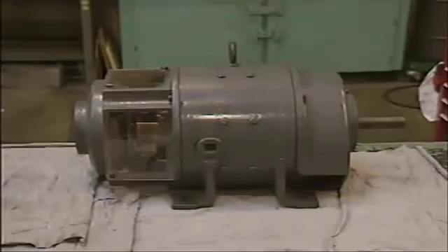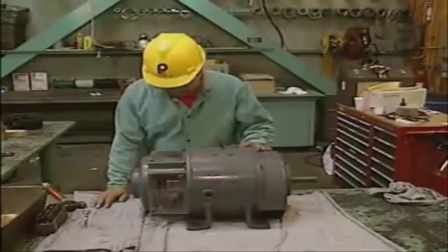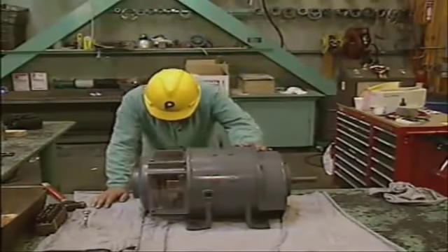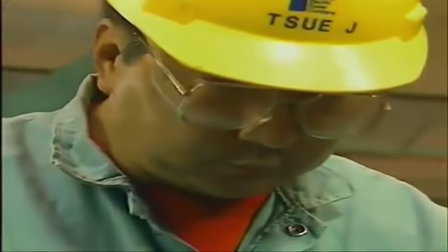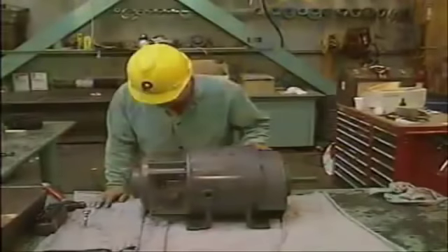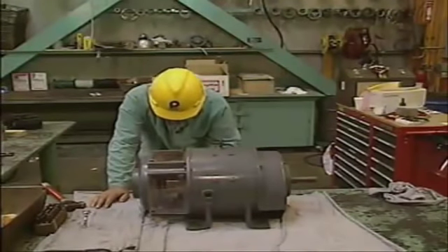In this part, we'll see how a DC motor can be disassembled for maintenance. When overhauls are required, DC motors are stopped, de-energized, and locked out and tagged according to approved procedures, and in many cases, moved to a workshop. Work area preparations may include spreading a cloth on which to place the motor.